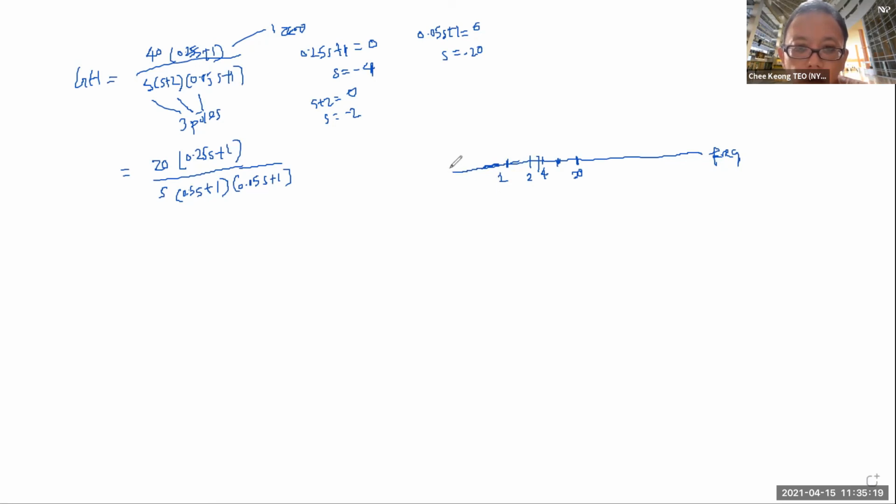So basically, you start with 0 dB, go all the way down here. Then at 4, you move up by plus 20 dB per decade. To check 20 dB per decade, let's say 4 to 40, then you check, is it at 20 dB? Yes, 4 to 40, 20 dB here. So it's 20 dB per decade. That's your first zero asymptote, right?